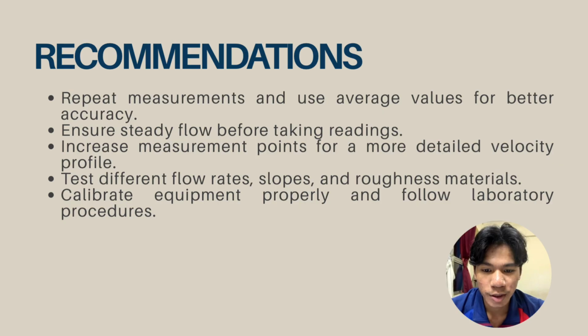For future improvements, we recommend repeating the velocity measurements and using the average values to improve accuracy. The flow should also be allowed to reach steady state conditions before taking any readings. In addition, more measurement points can be added to obtain a more detailed velocity profile. Future studies can also investigate different channel slopes, flow rates, and roughness materials to better understand open channel flow behavior.